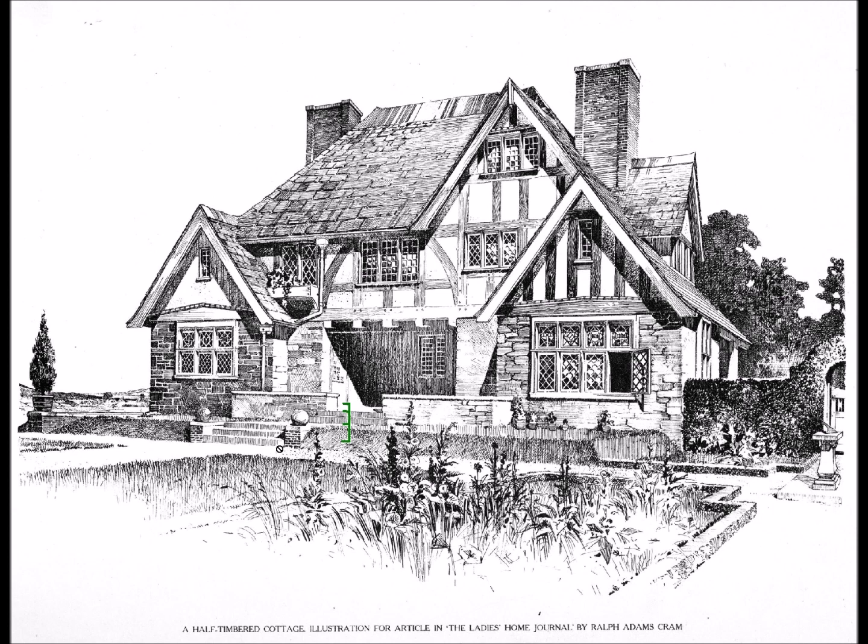These are outdoor steps, so probably they're about 6 inches high. Typically stairs inside a house are between 7 and 7 3/4 inches, but a stair in a landscape is typically closer to 6. So I'm going to assume 6 inches, which puts the floor of the house inside 3 feet, 6 times 6 inches above the ground surface outside. So that's one reference we're going to use.